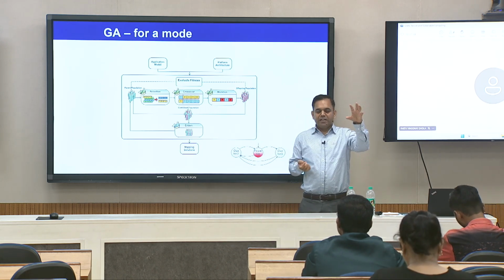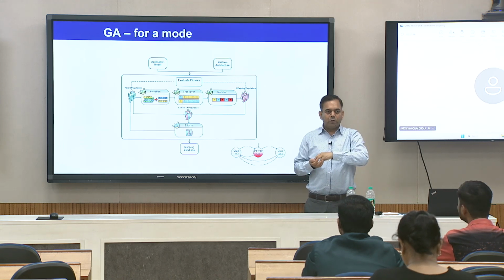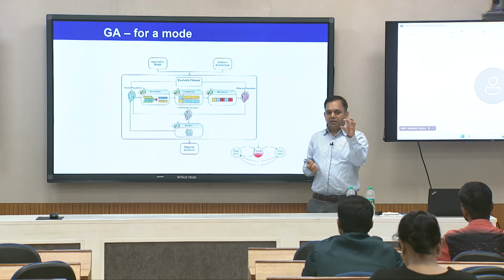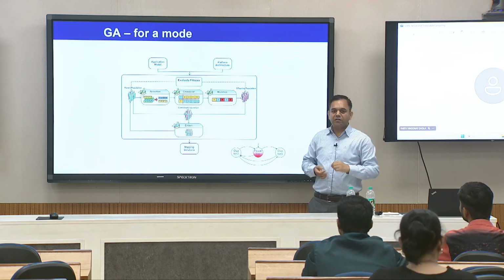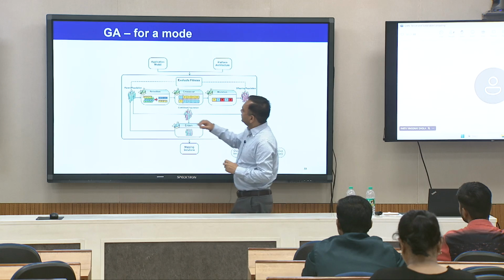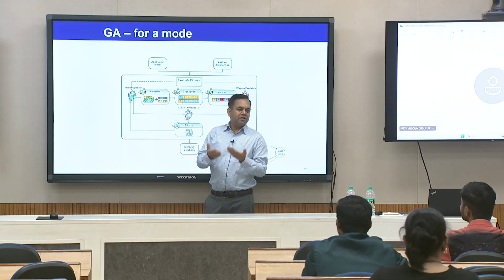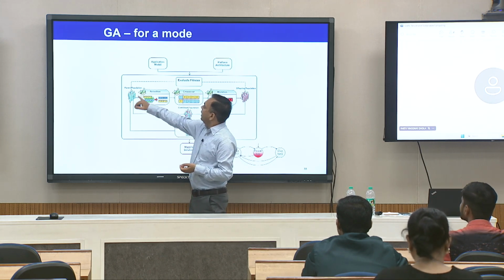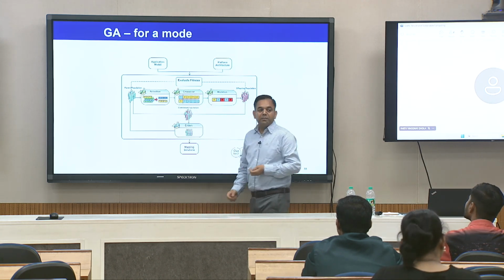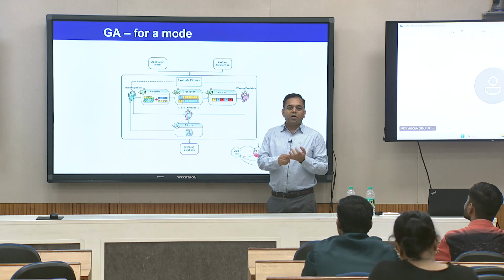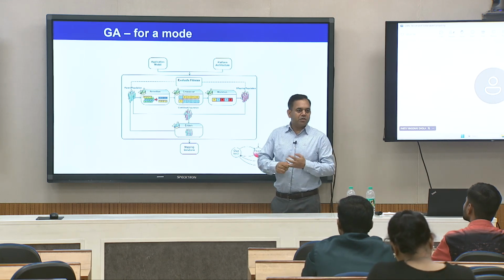If it is a 4 core platform, there are many possibilities to map those 18 runnables: maybe all on 1, distributing on 2, distributing on 3, and so on. You generate some initial design points, and then you evaluate all of them. Evaluation can mean maybe energy consumption or timing.